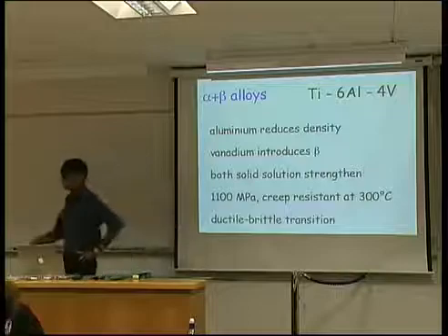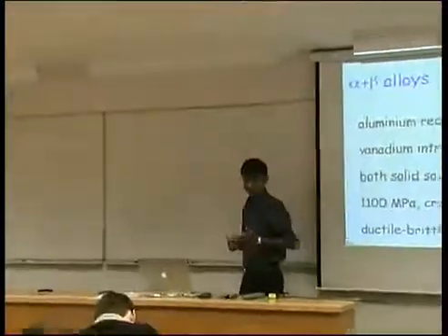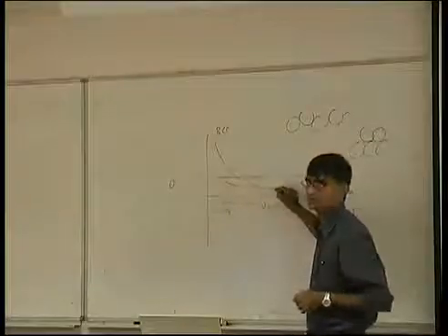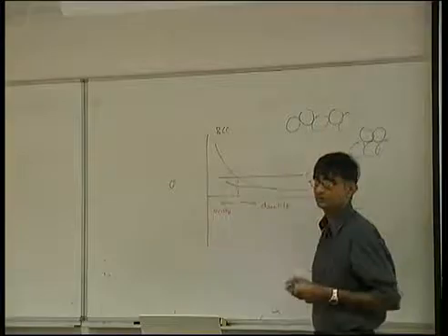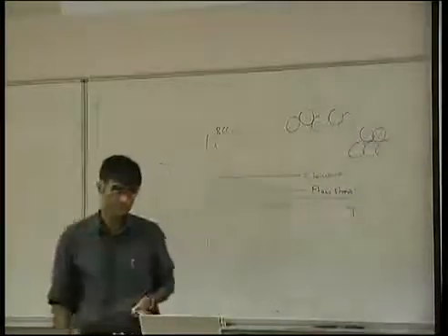If I drew the corresponding flow stress for, say, austenite, which is face-centered cubic, it would always be less than the cleavage stress. And that's why you don't get a ductile brittle transition in nickel or iron, which is FCC.